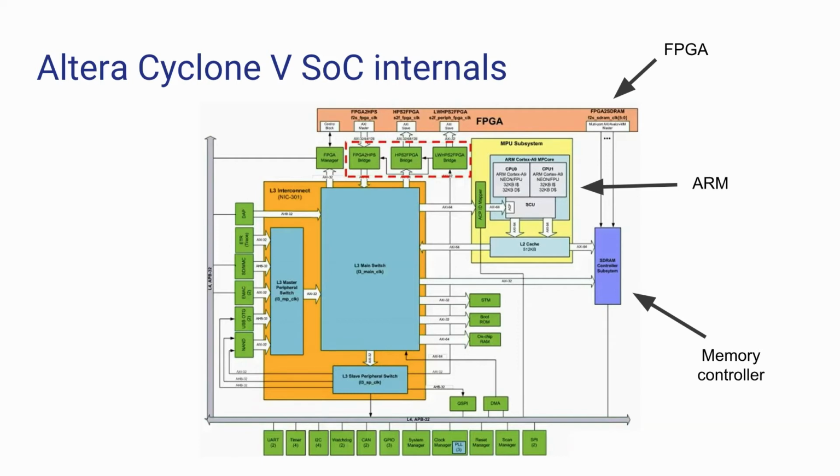So they make System on a Chip, where they stick the CPU and everything you need on the chip itself. It's got CAN bus and UARTs and timers and SPI and I2C, and everything you want, they just stick in hardware. And this is part of the 3,800-page manual, is how to access all these things. And we didn't use most of that stuff. I think we used I2C maybe? I2C for some of the I/O stuff.